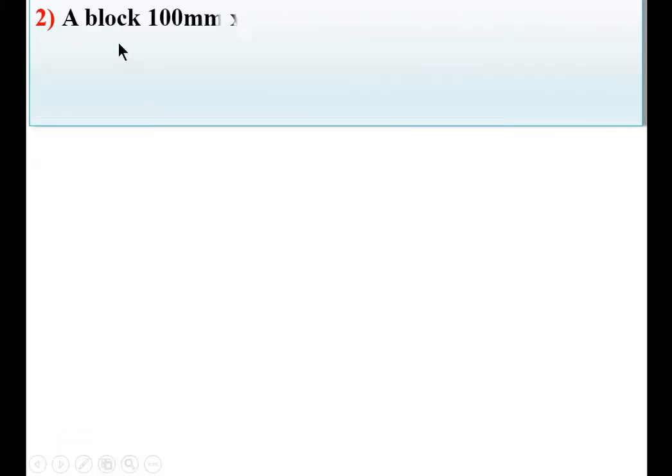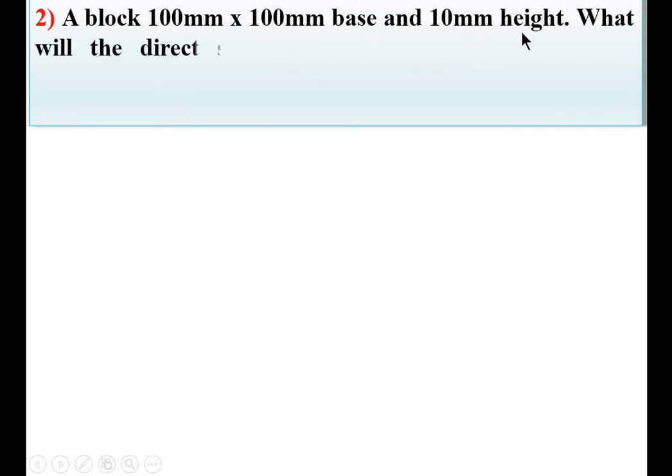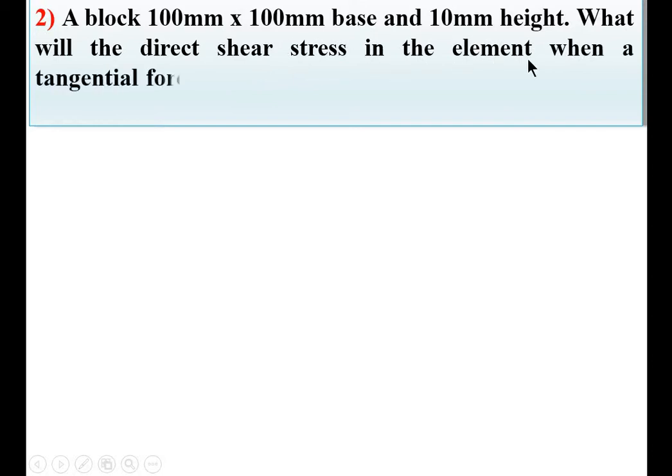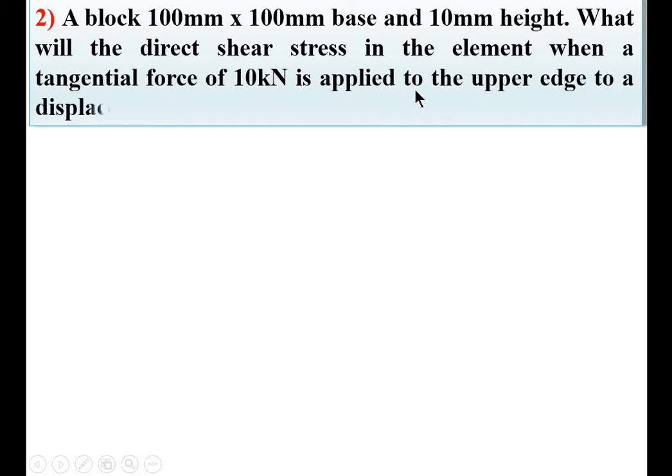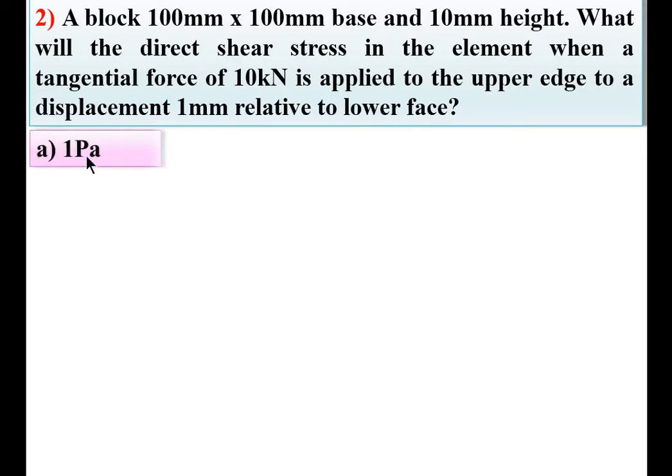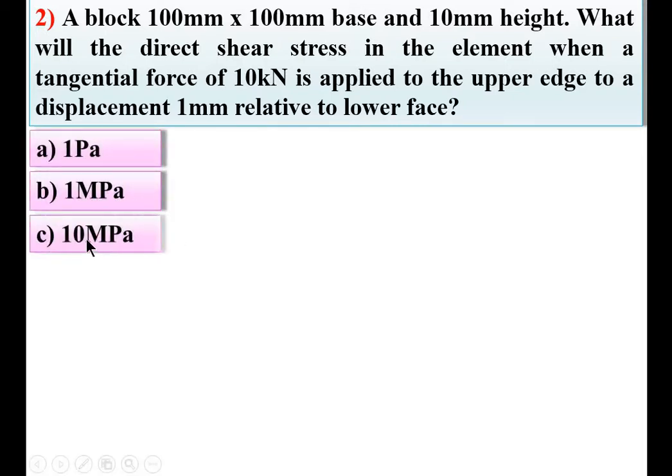Next, a block with 100 mm by 100 mm base and 10 mm height. What will be the direct shear stress in the element when a tangential force of 10 kN is applied to the upper edge, causing a displacement of 1 mm relative to the lower face? Options: 1 Pascal, 1 megapascal, 10 megapascal, 100 Pascal.